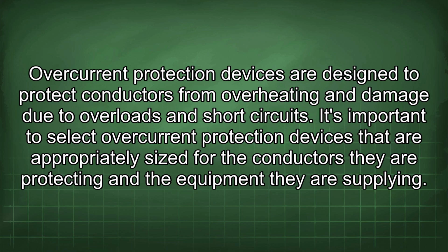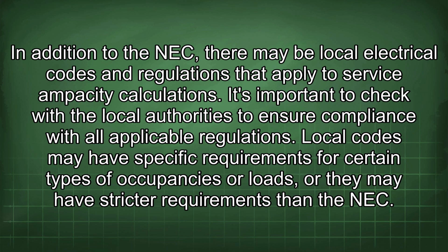It's important to select overcurrent protection devices that are appropriately sized for the conductors they are protecting and the equipment they are supplying. In addition to the NEC, there may be local electrical codes and regulations that apply to service ampacity calculations. It's important to check with the local authorities to ensure compliance with all applicable regulations.